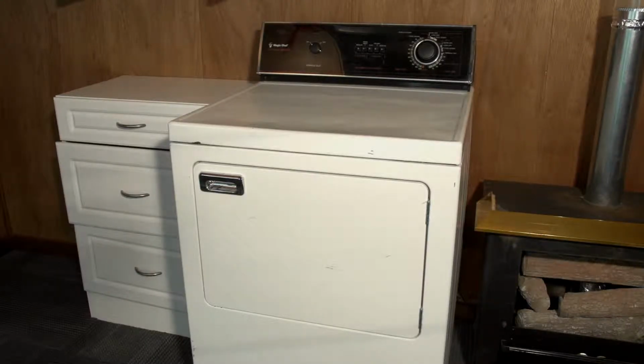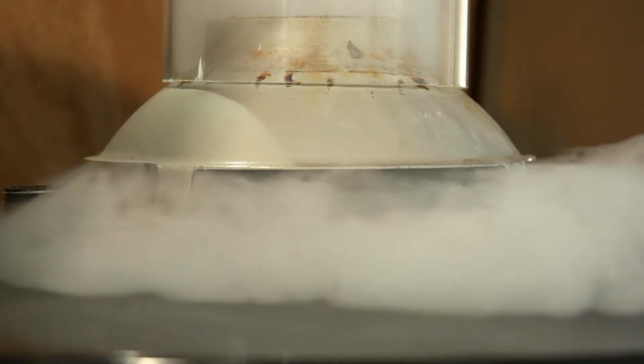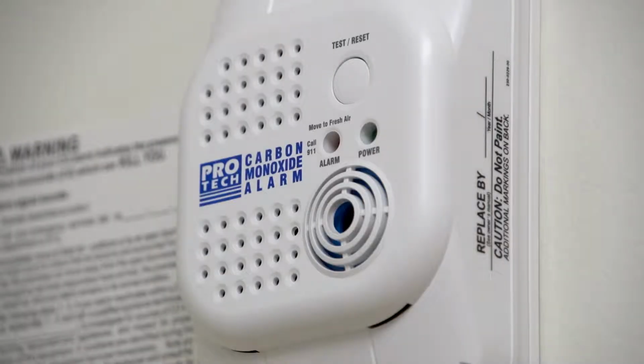Now let's observe what happens in our CAS area. We have combustion gases coming back into the house, as we can see above our water heater. This means that carbon monoxide and flue gas is being pulled back into the house. And really, what Mom and Dad have sitting right there next to it in the form of their furnace is a very expensive carbon monoxide distribution system. Now, if Mike was smart, hopefully he installed a carbon monoxide alarm in that house. And it is sounding now, alerting the family to the danger.